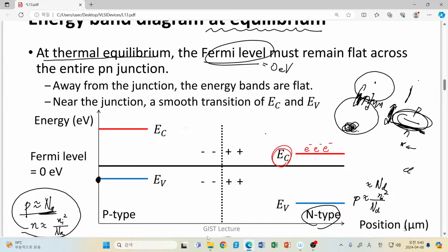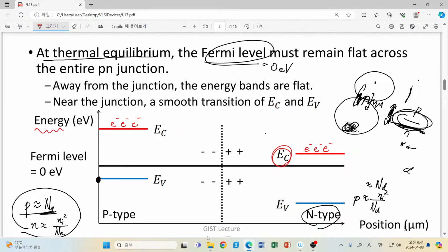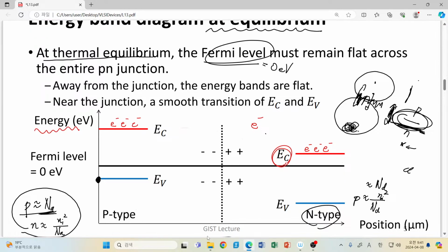The p-type is seen as the less attractive part. Okay, so always, since this energy is the energy seen by our electrons, they want to keep the lower energy region. So if we pick up one electron and ask it, where do you want to stay?